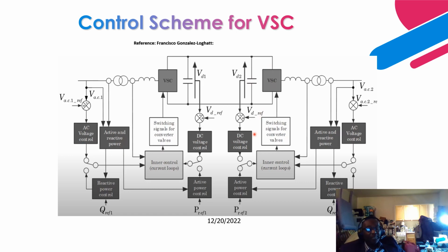Based on what is measured, we are measuring from here, and we have a dispatch reference point. From what is measured, we calculate our IQ and ID, our quadrature axis current and our direct axis current. We have a reference point for the direct axis current and quadrature axis current, and we have a measured point, so we can calculate our error.